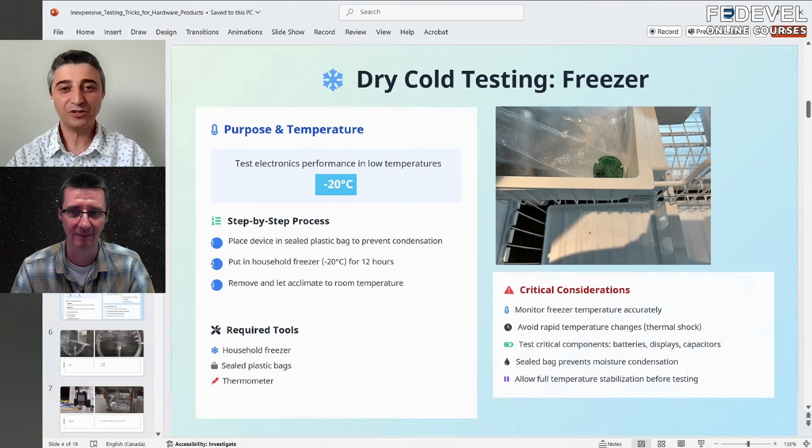Now, you know there is an issue in the whole design, but you're suspecting three or four components, like a processor or a RAM. You can go exactly with the nozzle and spray that specific area, and if it fails, you know this is where your issue is. It could be some I2C or some DDR4 that is jamming up, or a sensor that is not responding and is just stuck. So using the spray is really super helpful to pinpoint directly where the issue is, rather than just knowing there is an issue.